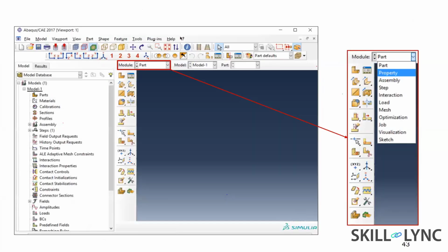So this is a look at the Abaqus GUI, the graphical user interface. And you have a very compartmentalized approach to the interface. Like we looked at the various components of the Abaqus model earlier, and so we have this drop-down menu where we can switch from one module to another. So basically, if you are doing the geometry definition, you go to part, and you'll have a context menu like this to create the part, and then next, the properties, when you want to define the material of the body, you will go to the properties module, and so on. So you have a very compartmentalized and very intuitive interface to build your Abaqus model.